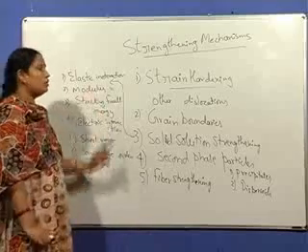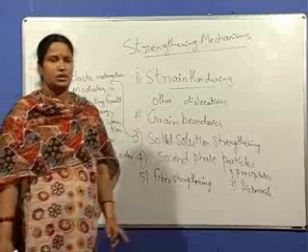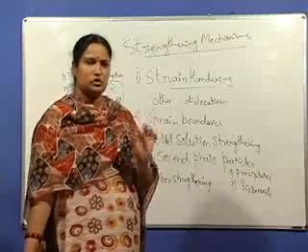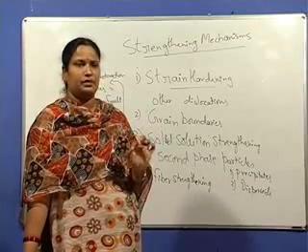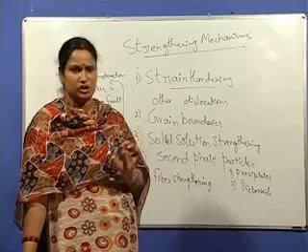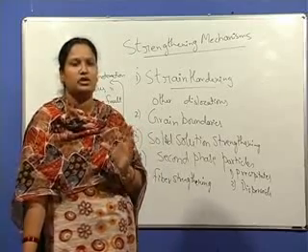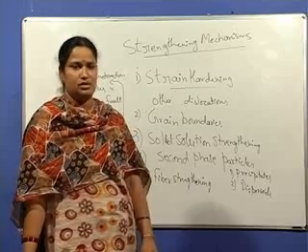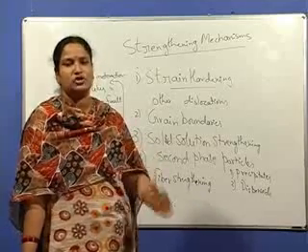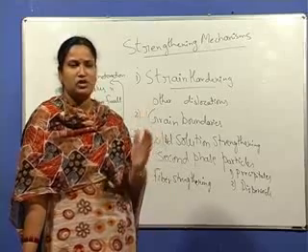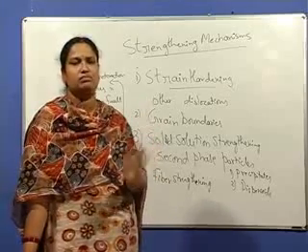The second one is modulus interaction. Because of the presence of solute elements, if they cause any modulus change locally, that changes the modulus of the crystal. So that also creates strengthening because of the modulus difference between the solute and the solvent.